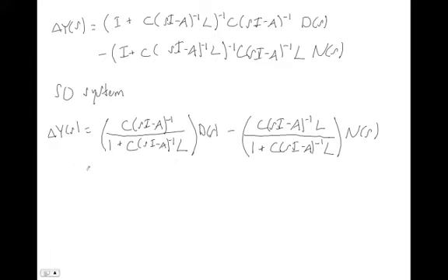Okay, so now if we limit ourselves to a single output system, we can see really clearly the way the observer gains L come into play in the transfer functions from the disturbances on the states and the noise on the sensors. When you start looking at this, you start saying, what would we like? Ideally, we don't want the disturbance or the noise to affect Y. We would like it if our Y was perfect and this delta Y was always 0, regardless of D and N. So we'd really like both of these to be 0, ideally.